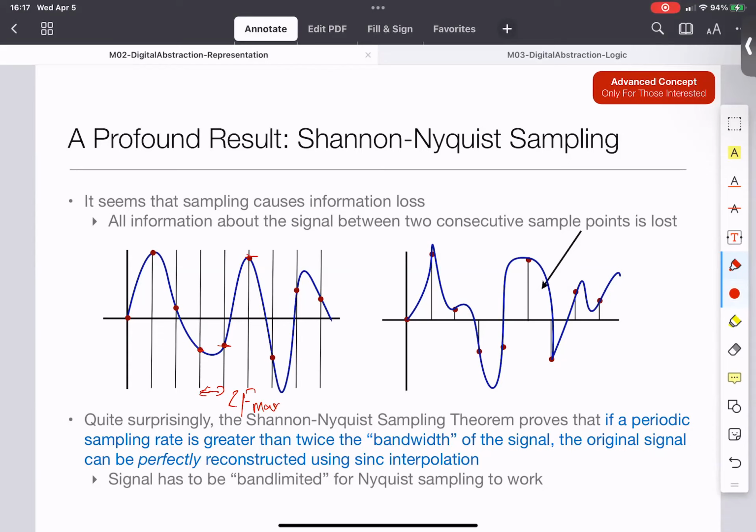By that, what I mean is, if I were to ask you what the value is out here, then just given that finite set of values, I can reconstruct it. Those of you in your signal processing classes may have already encountered it, or you will encounter it. But in this case, what we're basically saying is, if my signal has a well-defined highest frequency, I can reconstruct it.